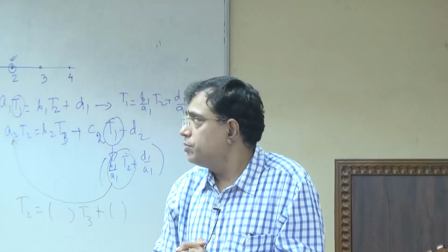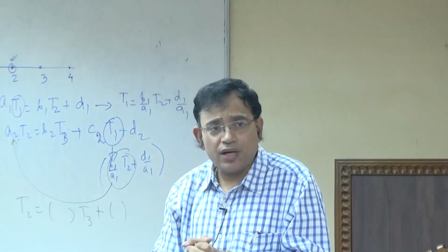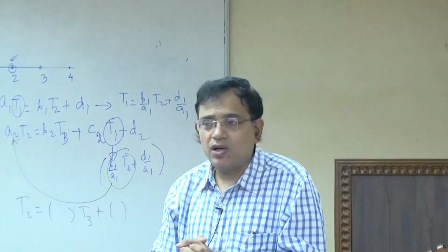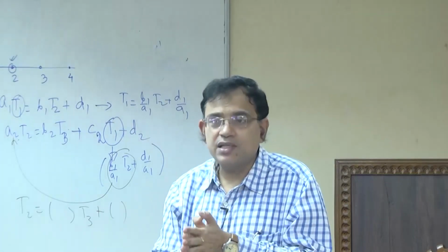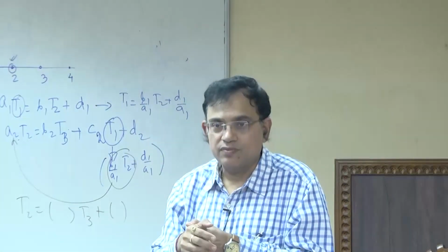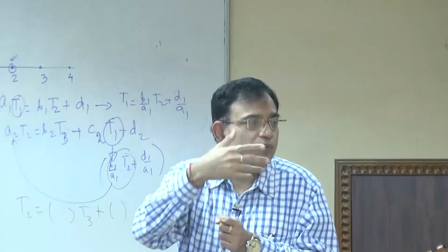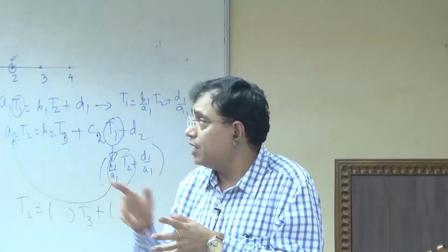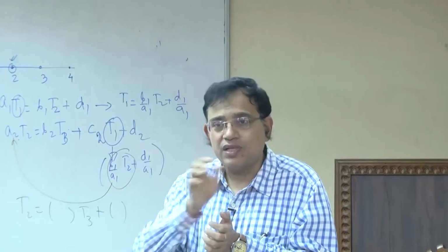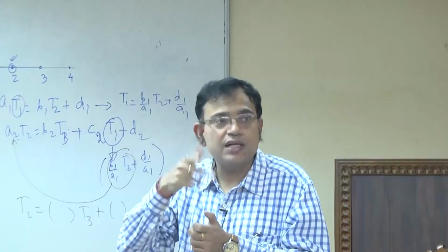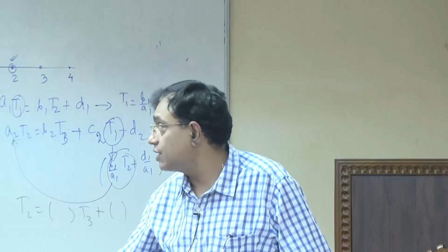Sometimes what people do is prefer an implicit scheme. Why? Because before standardizing a CFD problem you have to make a lot of trials. So, to make the trial you can keep a coarse time step and see at least it is giving physically the correct thing, but with the explicit scheme you cannot keep a coarse time step, because that can give you wrong results.